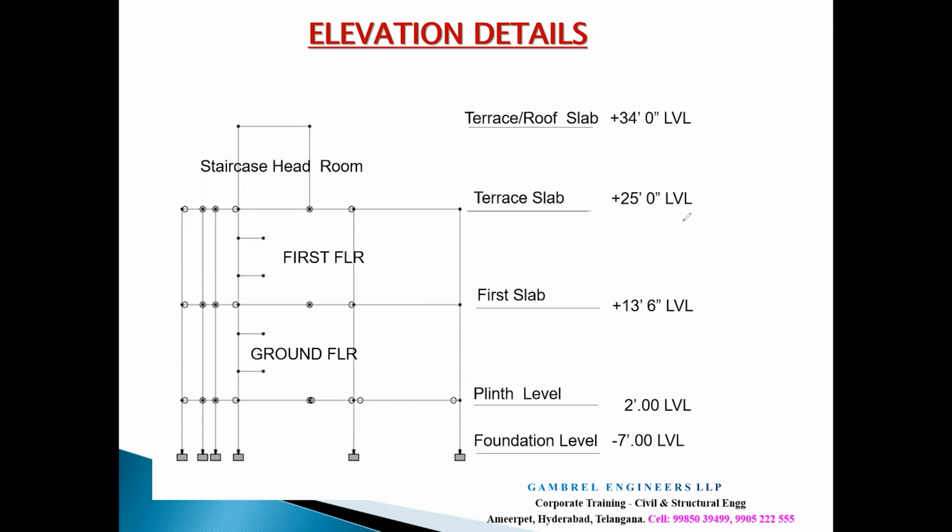Not only this, you are also going to have a false ceiling. There is a false ceiling design, and there is fixing a fan, and so on. So considering all these things, it is advisable to have at least 11 feet height. Having 11 feet height is absolutely fine. Having more than 11 feet, like 11.5 feet, is also good. But it is not for mid-rise buildings. It is for only 2 floor or 3 floor buildings.